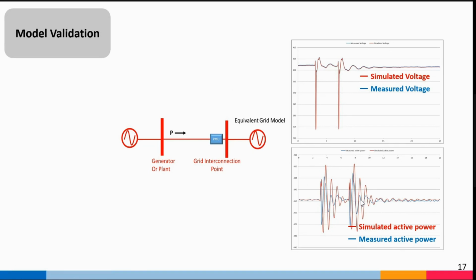So this is one of the major applications of synchrophasor data in compliance management, because the Indian electricity grid code, the 2023 version, has introduced that the generator must supply the validated model. Based on the data they provide, the system operators check during an event whether it is properly matching with the system.